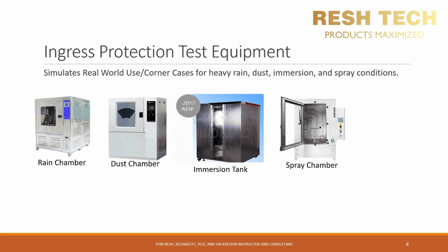Another example of ingress protection test chambers is a spray chamber, which simulates your IPX up to your IPX6 type ratings. Again, there is a multitude of different types of spray chambers and spray booths, and the pinnacle of ingress water protection is the IP9K test, which is tested for with a steam high pressure water system. So kudos to you if your product sealant can hold up to that test. That's a very impressive product, and you've put a lot of work into the design, so good work there.